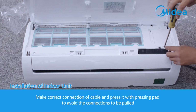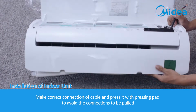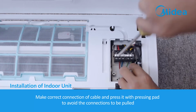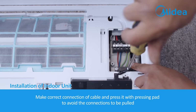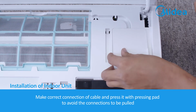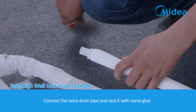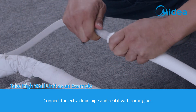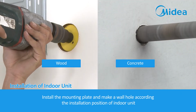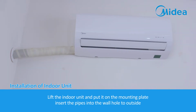Make correct connection of cable and press it with pressing pad to avoid the connections to be pulled. Connect the extra drain pipe and seal it with some glue. Install the mounting plate and make a wall hole according to the installation position of indoor unit. Lift the indoor unit and put it on the mounting plate. Insert the pipes into the wall hole to outside.